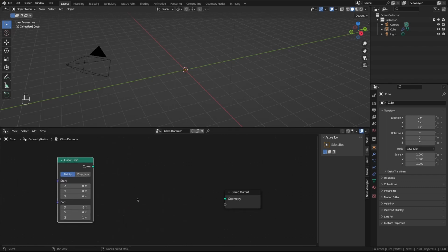And we want this to go out along the negative y-axis, just 1 meter. The reason for this is if it goes out on the positive y-axis, then when we form the surface, it'll be pointing in the wrong direction. It's just one of the advantages of being able to look into the future. And the other thing is, as we shape the curve, we'll shape it along the negative x-axis, so that way the detail goes in, as opposed to if we did the positive y-axis, the detail will go out and our jar wouldn't have a bottom. You'll see that as we go along.